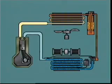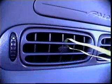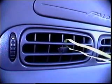This vaporization must take place inside the vehicle in a unit which can become cold itself and can be positioned so that the warm air inside the vehicle can be drawn into contact with it and give up its heat. This is the function of the evaporator. Once cooled, the air can be redistributed inside the passenger compartment.